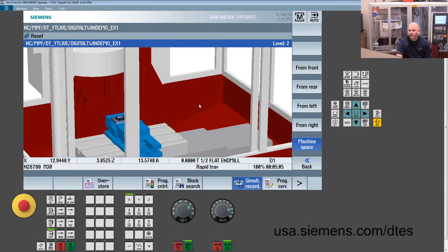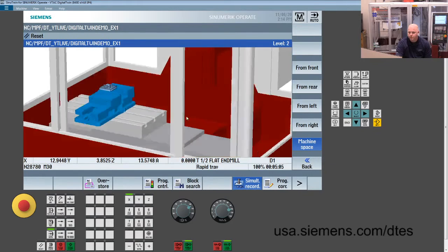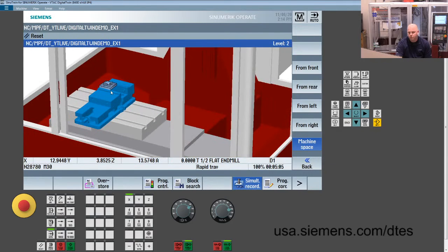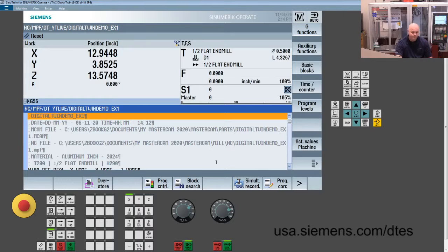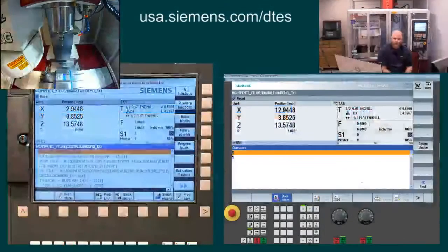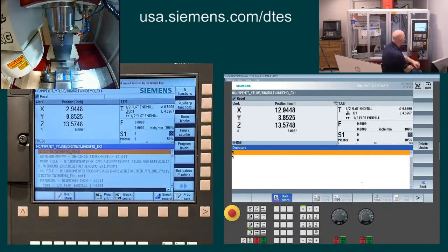we are evaluating the full tuning profile of this machine tool here inside of our digital twin, because we know everything about that machine. So if I go over and look at my cycle time, I now have a 5 minute and 5 second cycle time, as opposed to my original cycle time over in my CAM system of 4 minutes 19 seconds. Now, what I didn't tell you is the actual part program we were running on the physical machine is